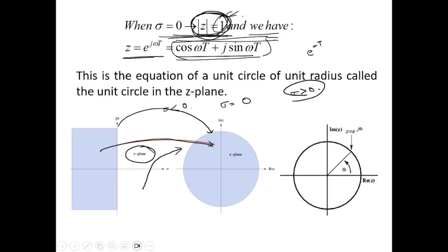Okay, it becomes 1. So what does this signify? This whole frequency component, which is from minus infinity to plus infinity, has mapped into 0 to 2 pi. After that, the other frequency components will again be moving onto this unit circle itself. Okay, now when that happens, it becomes a many to one mapping. So that means one frequency in the analog domain will be mapped into multiple digital frequencies, both in the positive domain and the negative domain also.